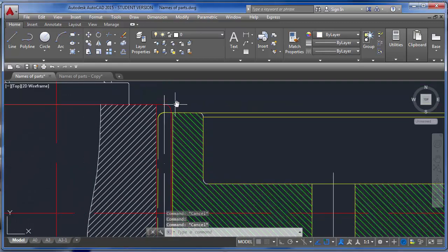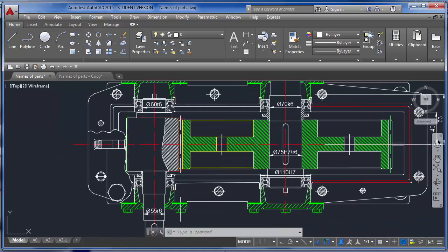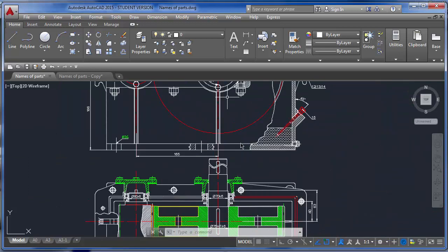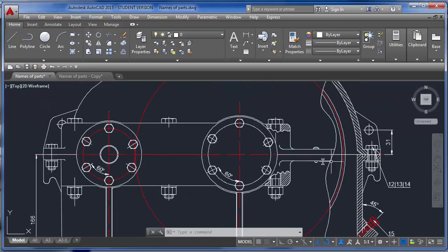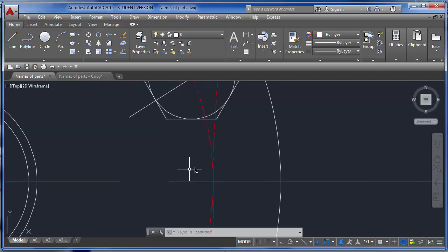But when you draw, we normally draw the driving gear on top and the driven gear on the bottom, because you have cut it all the way through the middle, right? So we have the driving gear and the driven gear. The driving gear's teeth will be on top, the driven gear's teeth will be on the bottom.